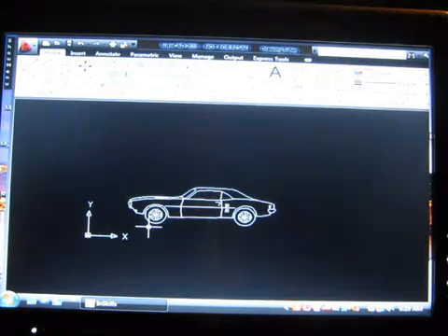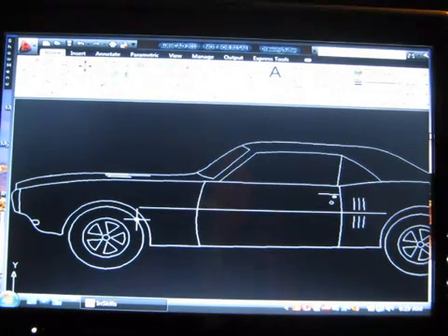There was a time in AutoCAD when you couldn't zoom in real time like this. You weren't exactly sure where you were going. Oh, it was terrible. But clicking and holding the scroll wheel will start the pan command. Using these two functions of the scroll and the pan will allow you to maneuver inside your drawing everywhere you need to go. There's one more thing that you can do with the scroll wheel. If you double click the scroll wheel, you will perform what is called a zoom extents. This will zoom your drawing all the way out so that you can see everything that is in your drawing.